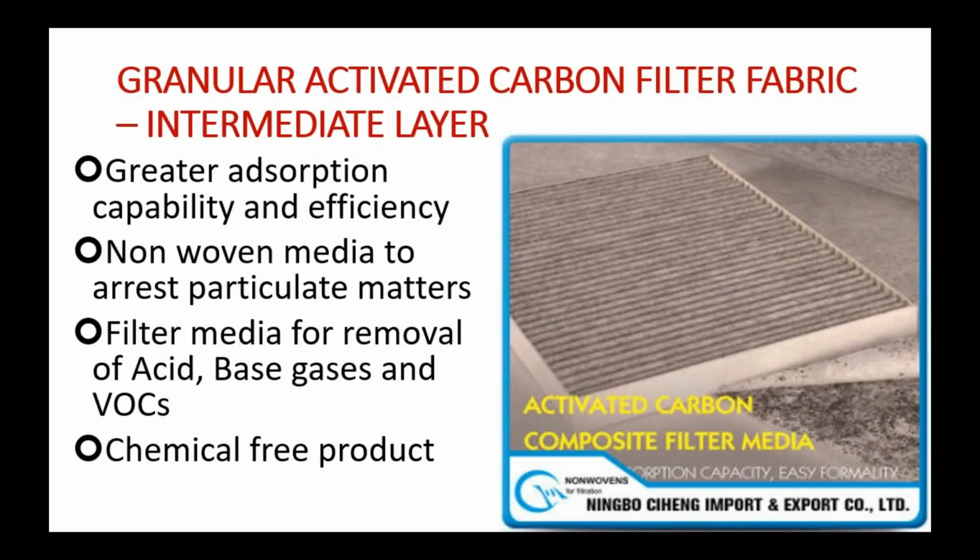So this intermediate layer after the polypropylene is granular activated carbon filter fabric. It has a greater absorption capability and efficiency. It is a perfect non-woven filter media to arrest particulate matters. So this is also a supporting filter media to arrest particulate matters. And it is the best filter media for removal of acids, bases, gases, and volatile organic compounds, whatever has been in reaction or which deposits on the surface. And it is a chemical-free product also.